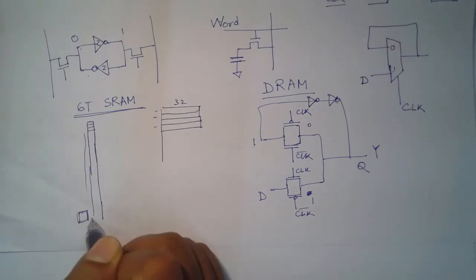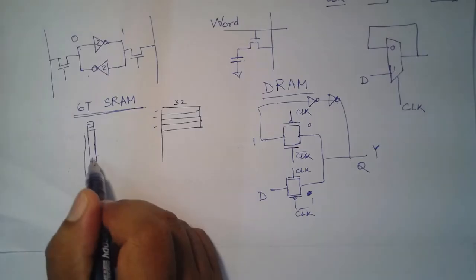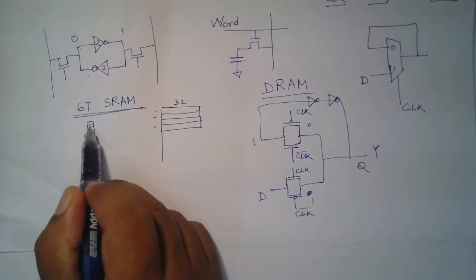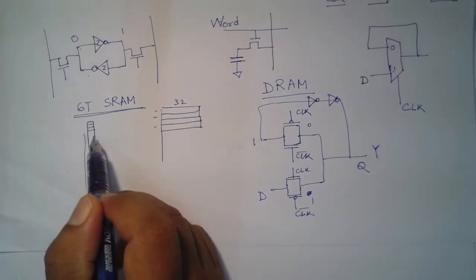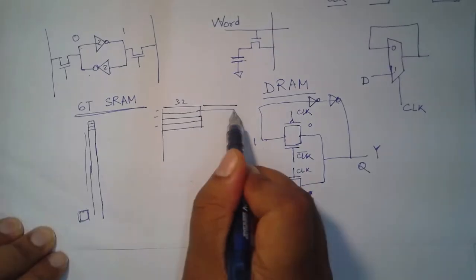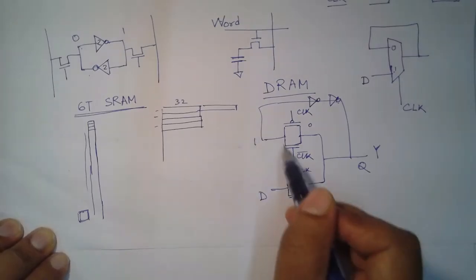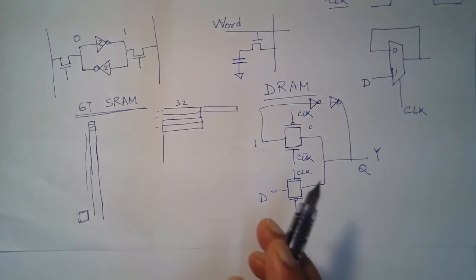Now what are the alternatives? So you can say that okay, the alternative can be that instead of storing one word in one row, you store multiple words in your row. That looks very logical. So basically instead of 32-bit you store maybe 64-bit or 128-bit in each row, and you try to make this structure as square or rectangle as possible, right?